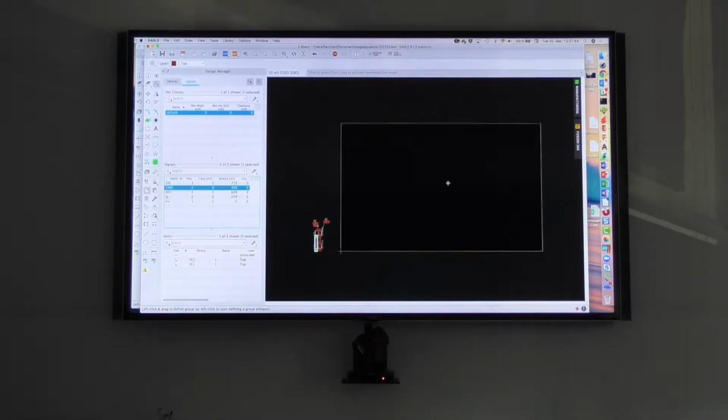But very important is, now you have to think about what am I designing. I should know, of course, what the components are, and I have to think about design rules. How is the board built? If I have two layers, then it's not a problem. I have a core like this one, I have copper here, I have copper there. If you know the manufacturing process of a board,